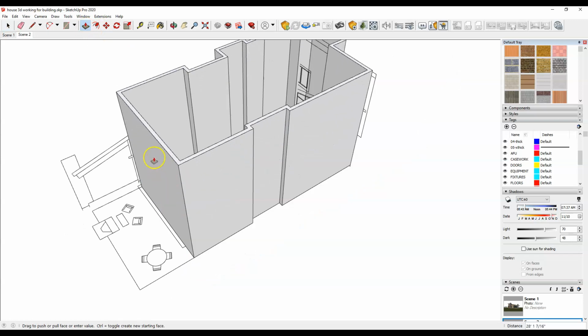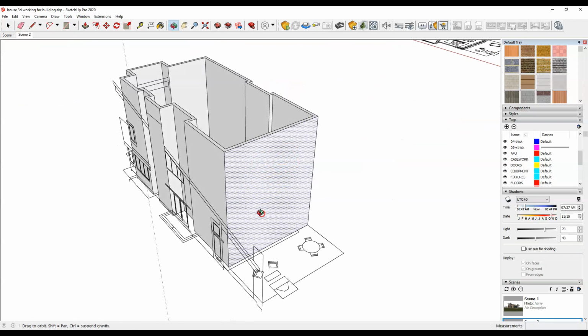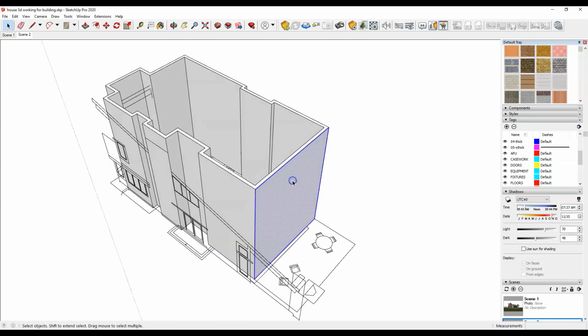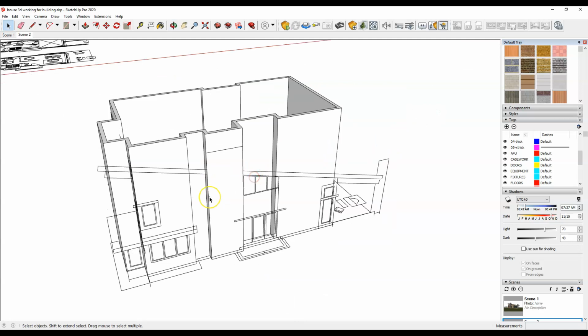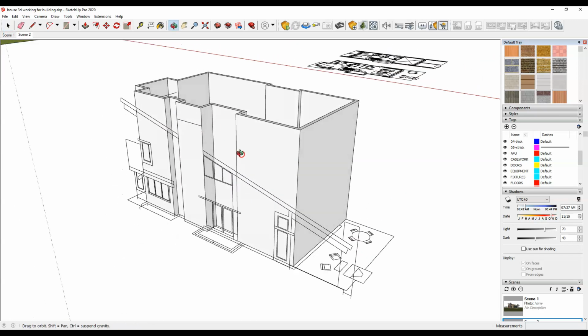Now all I'm going to do is simply push pull. Again, I'm not worrying about the roof. I'm going up higher than the roof, and I'm not worrying about the windows and doors. And so you made the walls. What I'm going to do is triple click, which is a quick way of selecting, so I can make this a group for the walls. So that's how you do all the walls. There might be other components you need to build, like a chimney out here and other such things. But for now, that's what we'll go with.